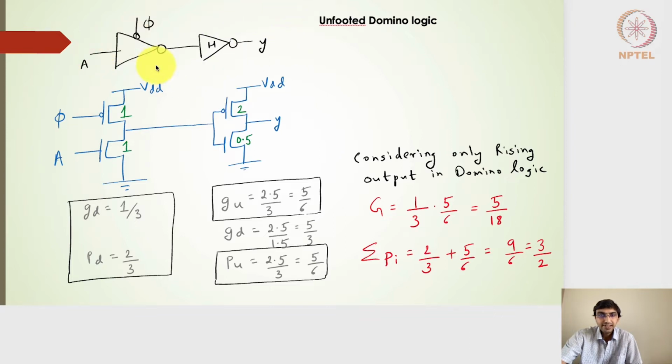In this particular gate level structure, the representation of the dynamic logic is nothing but a regular inverter gate structure, but because it's a dynamic logic, it is attached with a clock signal, and it is bubbled, which represents that this clock signal is going to the PMOS side of the transistor. This structure is cascading to the next regular inverter, and I've written an H here. H represents the high skew inverter. Let's talk about this high skew inverter.